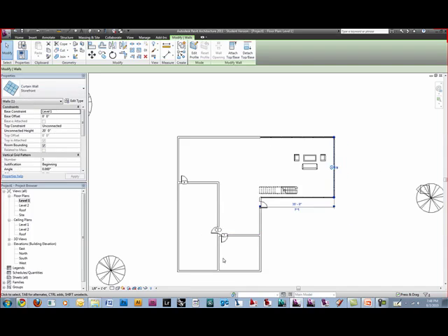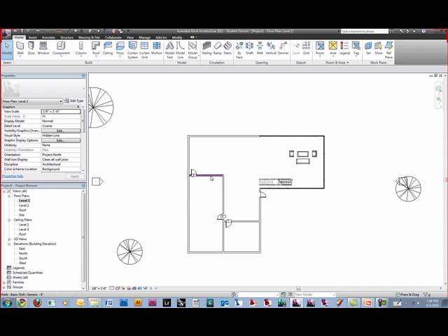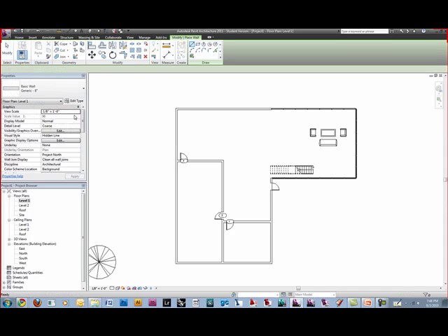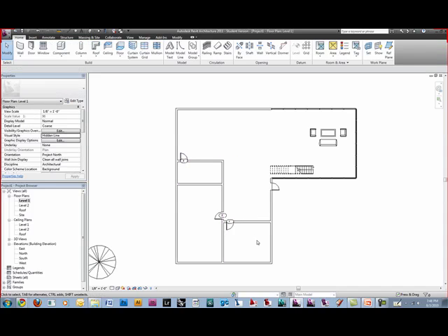All right, so let's say, put like a bed in there. Let's say, back in here, maybe there's a bed and this was a bathroom or something. A wall in there. What was the bathroom? There should be 2 bathrooms down here is what we were looking at. So generic, I'm gonna tell it to be 10 feet because I already know it. I don't want it to go up to the second level, or I could tell it to be top constraint level 2, and I'm gonna draw in an area right here because we actually did want a bathroom and then maybe 2 rooms, like an office and a bedroom, and this bathroom is shared between these 2 or something weird.